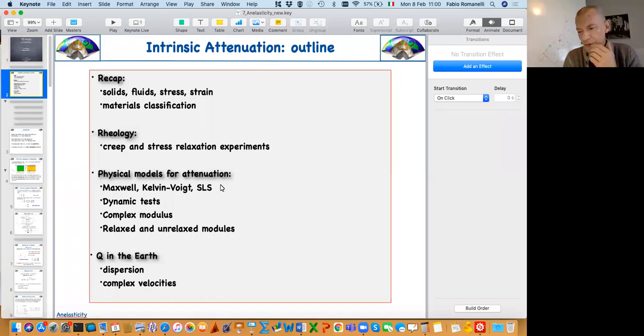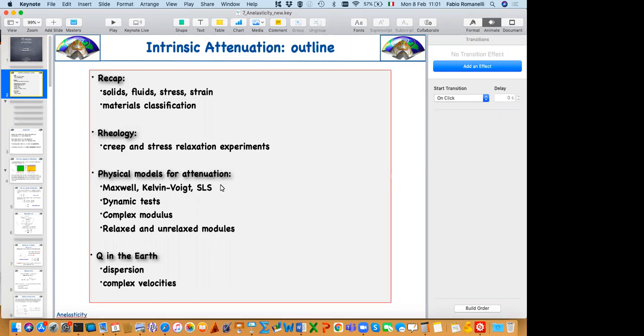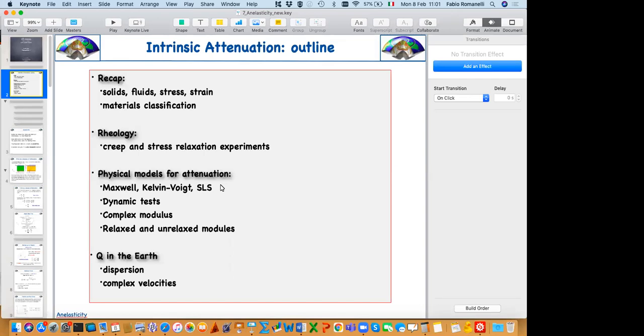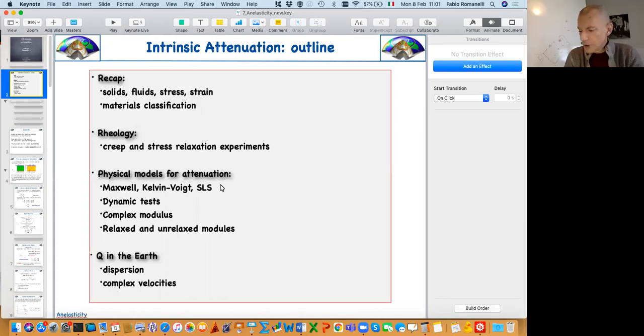about the topic, you can go much deeper than we did about the use of long period signals to better assess what, in principle, is MW. You know that, well, now you should know that the original definition of magnitude was an instrumental one, later known as ML, connected to the local conditions in California and to a specific instrument. So later we discovered with the expression, the logarithm of A over T, and T was referring to different periods for body and surface waves, and their limit, that was saturation.